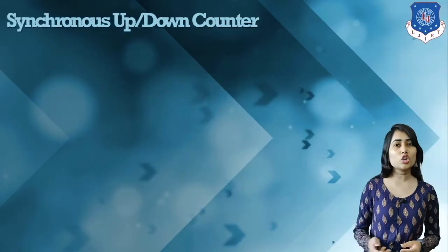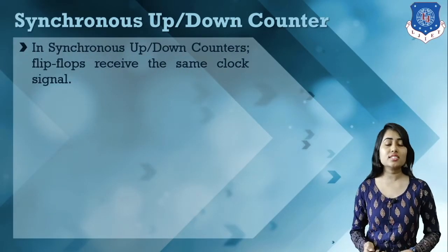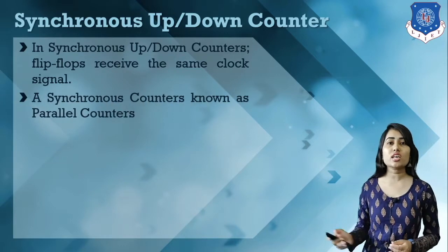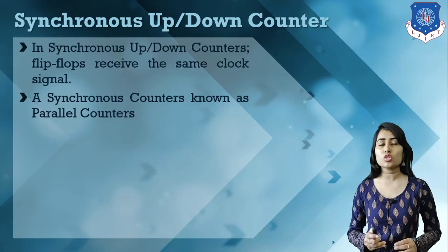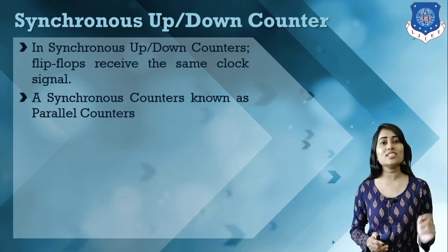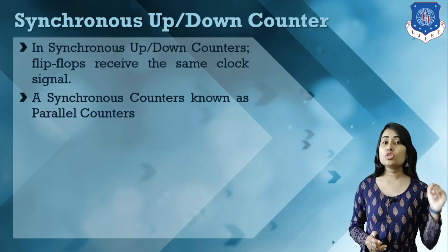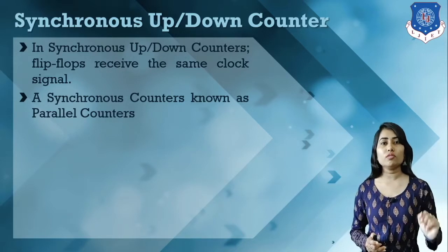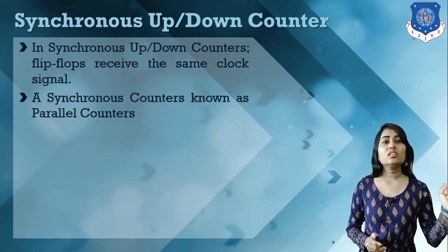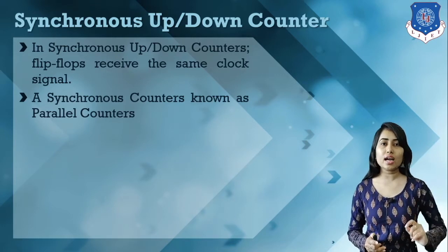As synchronous counters have the same external clock signal, this counter is also known as a parallel counter. All flip-flops receive the same external clock signal, so all flip-flops will work in parallel. All flip-flops will be triggered at the same time. That's why a synchronous counter is also known as a parallel counter.